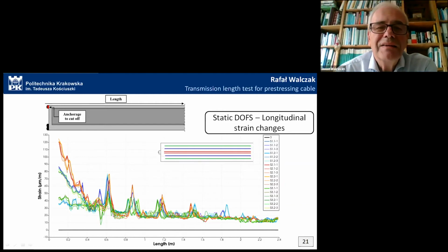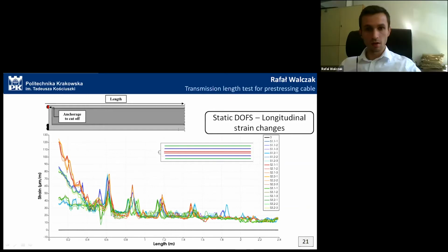Okay. Another question from Hussein Nasser. Did you apply a speckle pattern to monitor with DIC? Yes, of course. We applied the speckle pattern at the top. First of all, we had to install the optical fiber sensor, and then we painted it with a bright color and with a black speckle pattern, of course, to record the DIC strains. But unfortunately, the record of this method wasn't accurate.